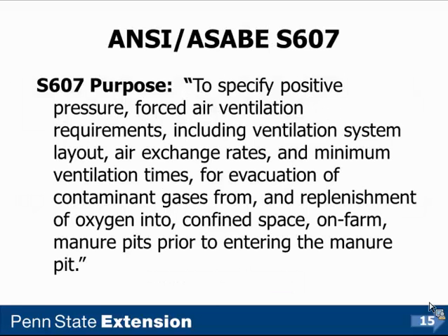The purpose of this standard, the S607 standard, was to specify, and I'm going to read this, positive pressure forced air ventilation requirements, including ventilation system layout, air exchange rates, and minimum ventilation times for evacuation of contaminant gases from and replenishment of oxygen into confined space on-farm manure pits prior to entering the manure pit.